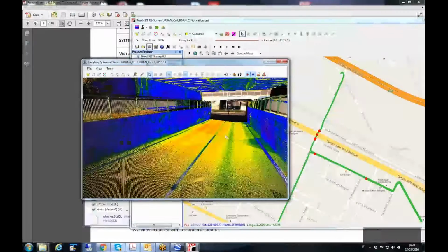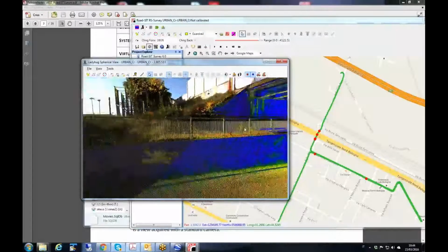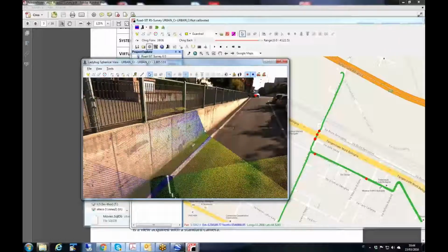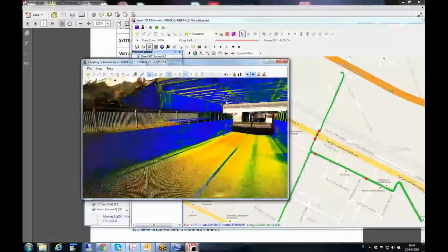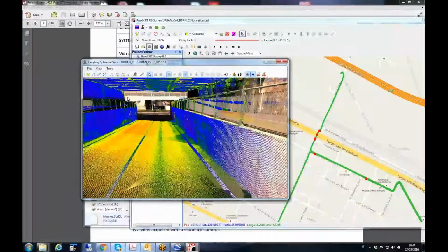In this case, you are snapping directly to laser point, or you can snap on a local plane. The software choose a group. Let me zoom in just to make it easier to see for you. The software choose a group of point, compute a local plane, and pick point on this local plane. Let me change the color of the guardrail because I cannot see here. Yellow on yellow.